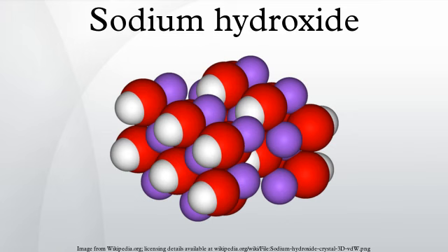Aluminium hydroxide is used as a gelatinous flocculant to filter out particulate matter in water treatment. Aluminium hydroxide is prepared at the treatment plant from aluminium sulfate by reacting it with sodium hydroxide: Al2(SO4)3 + 6NaOH → 2Al(OH)3 + 3Na2SO4.